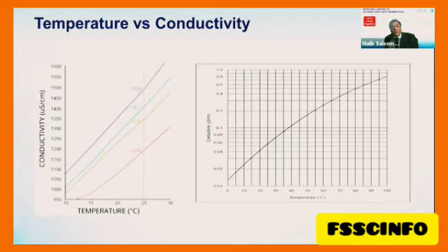But one thing I assure you: if you take a sample of the water, especially the RO product or the demineralized water, its pH is very unstable. If you measure online, the pH will be different. If you take it to the lab, the pH will be different, because water absorbs carbon dioxide from the air, and it makes carbonic acid, which leads to lowering of the pH.